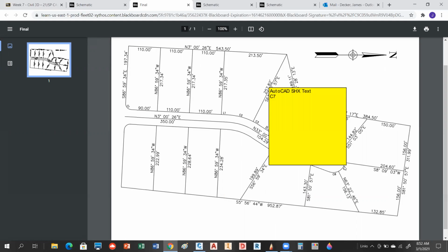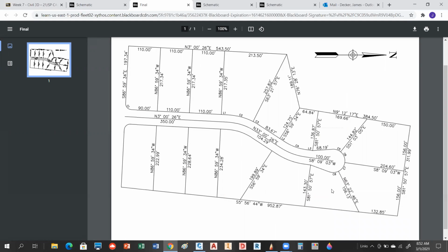Number one, this is a 40-foot radius. And notice it's 100 feet out from the end of that curve, so we're going to have to pinpoint where that is. And then the distance from where I call the throat, where that thing starts, to where that thing is tangent, that's 75 feet back. So I'm going to show you a couple of ways to do that. We're going to define this cul-de-sac first, and we're going to start busting this up into lots, okay?